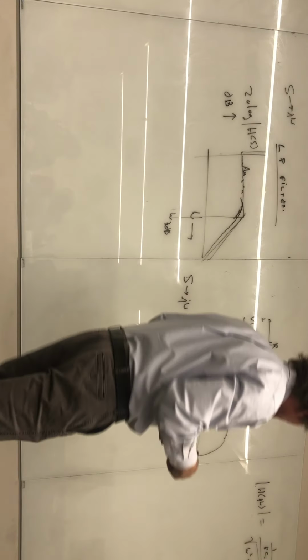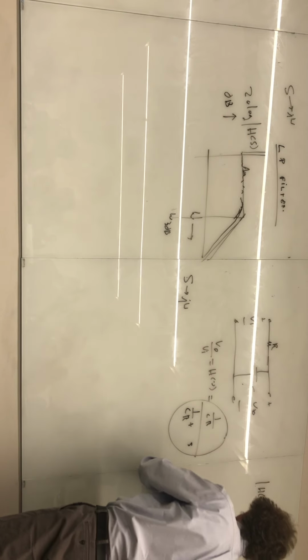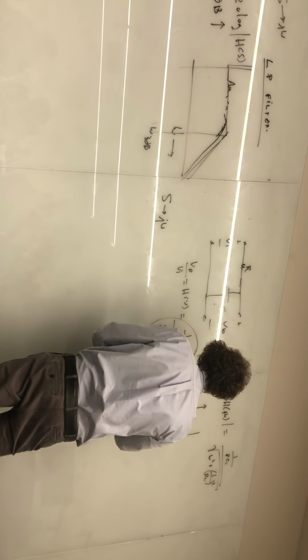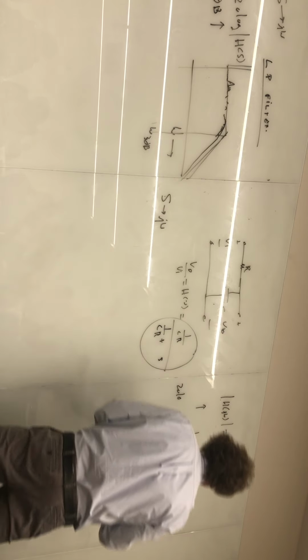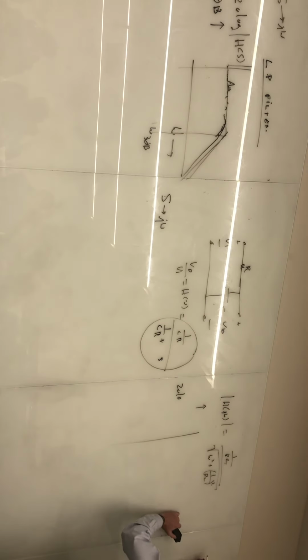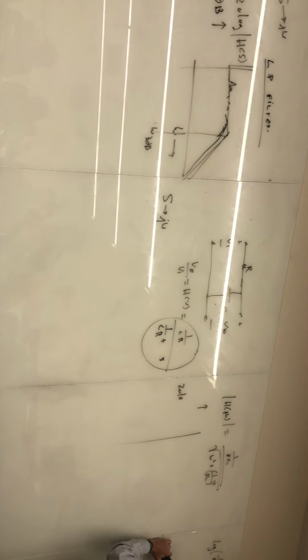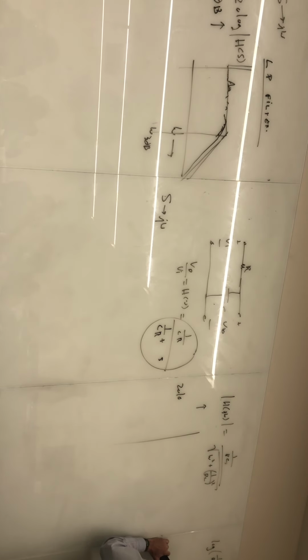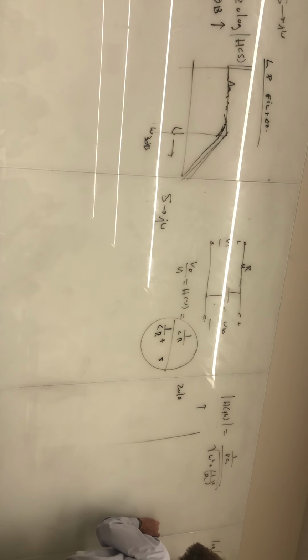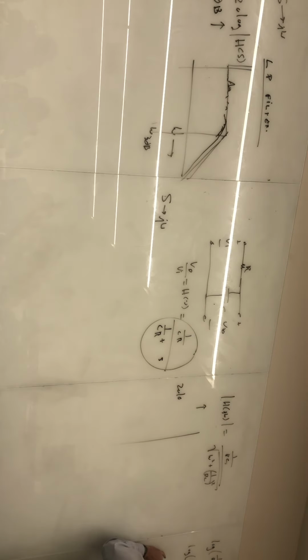So if I have that, now I can say, when I take 20, and I'm going to plot on this axis, 20 times the log, log base 10, of 1 over RC divided by the square root, or really it's going to be omega squared plus 1 over RC squared to the 1/2 power. When I take the log of that, and this is multiplying, log AB is log A plus log B, so it's log of 1 over RC, and then log of this.